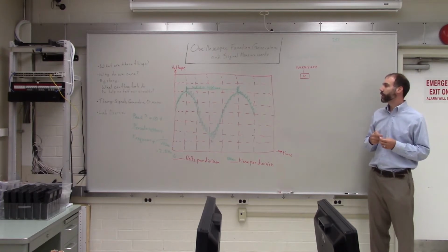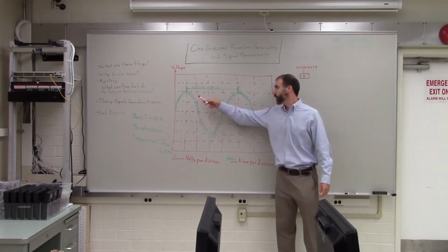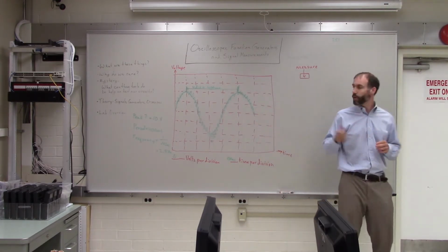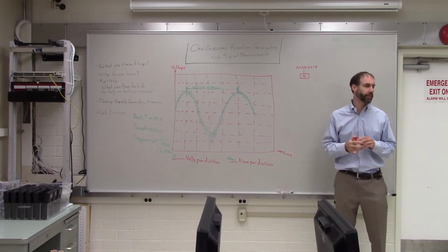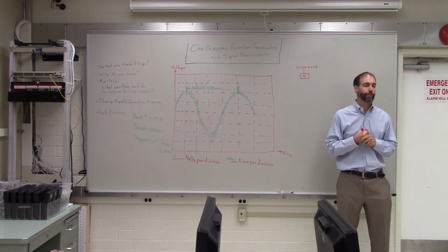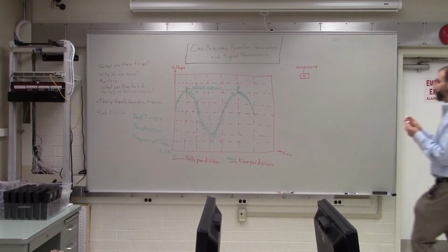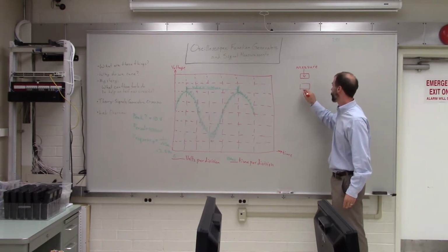Sometimes when your signal is like this, the measure functions get confused, like I already mentioned. So in that case, sometimes you have to use a different way of measuring your signal, and that's where cursors come in. So again, right underneath the measure button, there is a button that's labeled cursors.